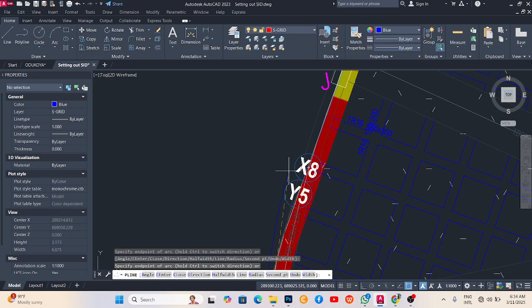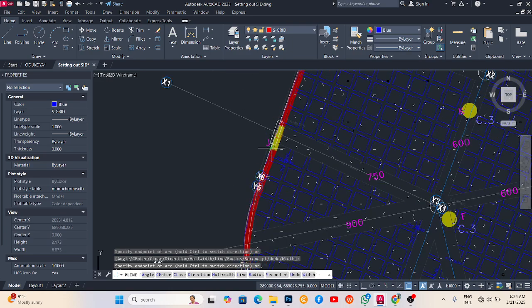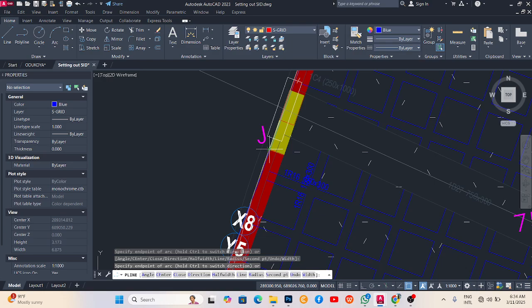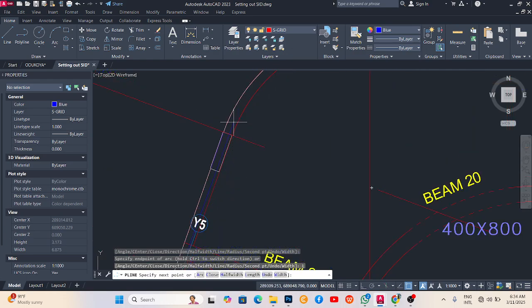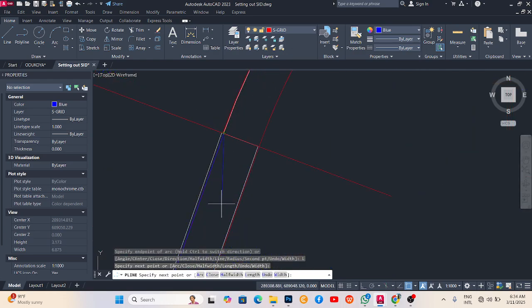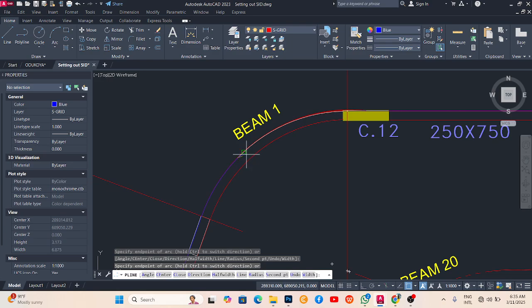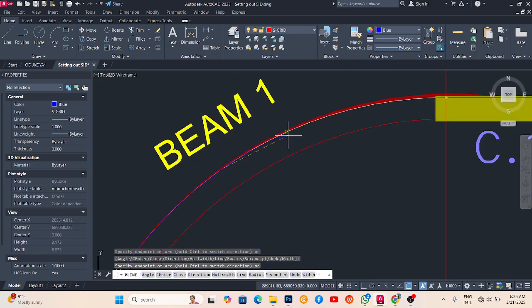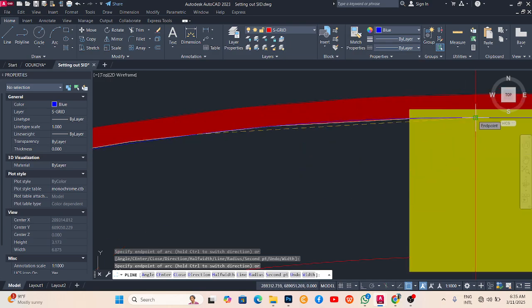So I want to quickly rush it so that I can round it up and show you guys the results. So this is where the straight line stops. So after here, I will click line again, then close it up to where I started from. I think it's okay. I still have some curves. So after this straight line again, I'll click arc so that I can close it up. So this is what we call advanced polyline compared to the one we checked in our first class. So I will just close it off from where I started from.